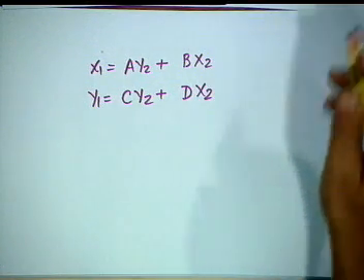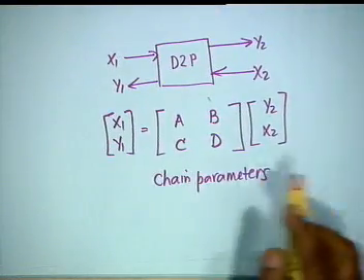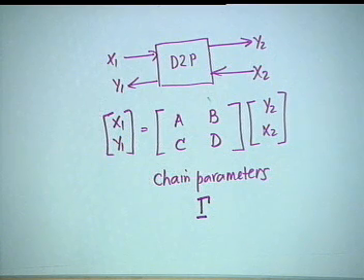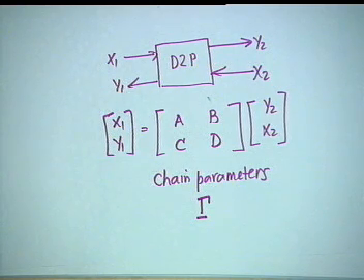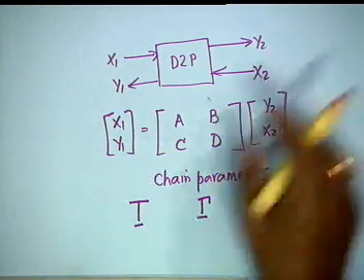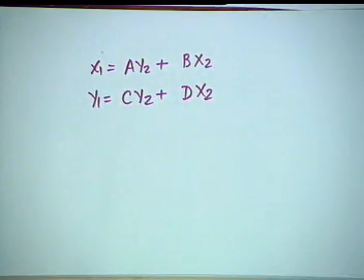The symbol that is given for this matrix ABCD is gamma, capital gamma. Do not confuse between capital gamma and capital T. Capital gamma, one of the hands is chopped off from T. Okay? Distinguish between T and gamma. T is the transmission matrix and gamma, capital gamma, is the chain matrix or the matrix of chain parameters.